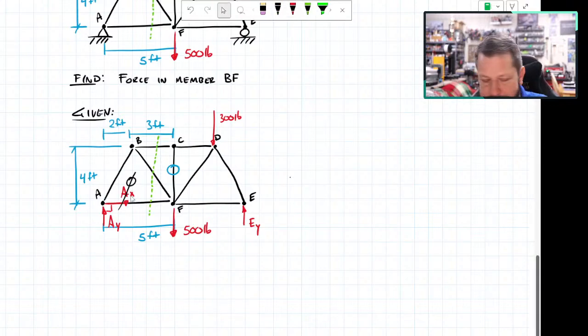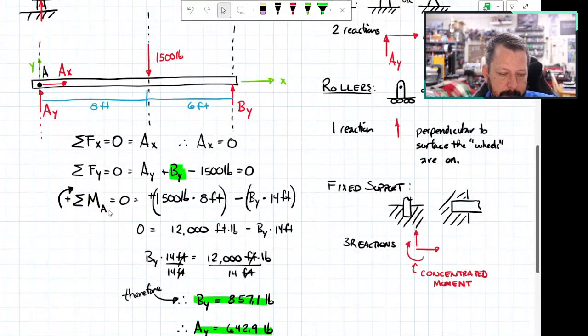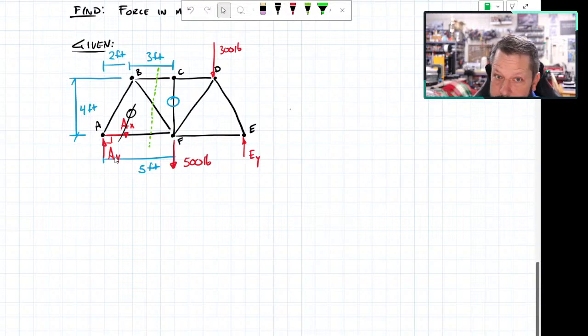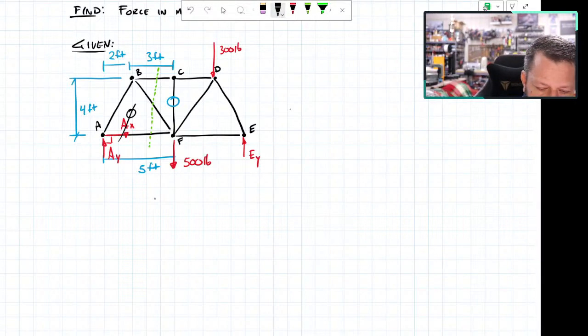If you're unsure, just solve for the moments about the pin, like I said earlier. You'll actually end up doing an extra step. Think about what goes on when you do the moments about the pin or whatever point: the AX and AY did not show up in the equation because their line of action went through that point. In this case, I want to solve for AY. I don't care about EY. So this one is actually better to do summation of moments about E.